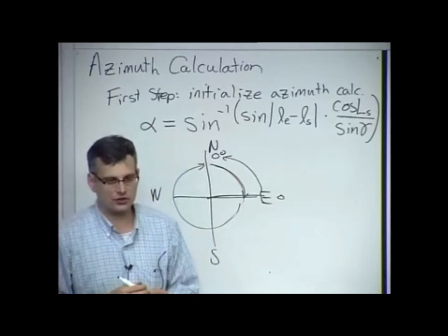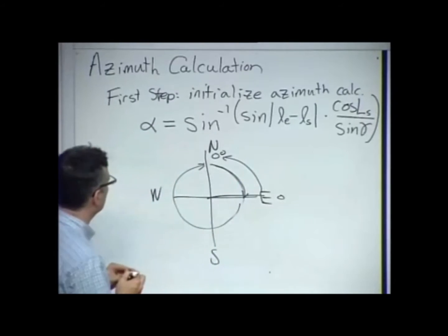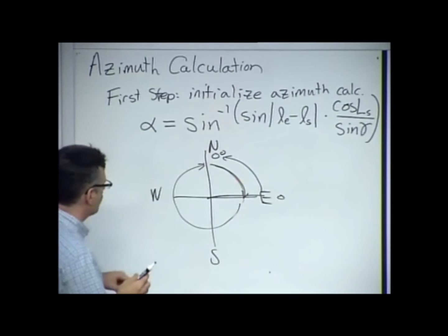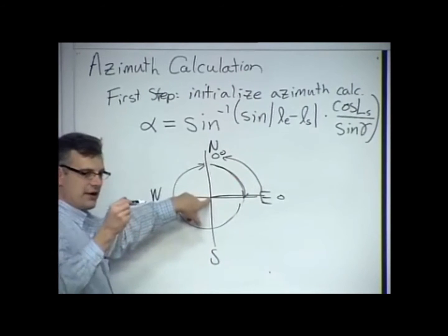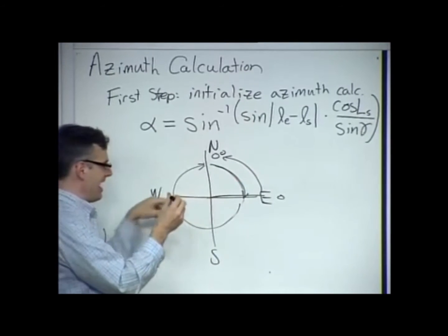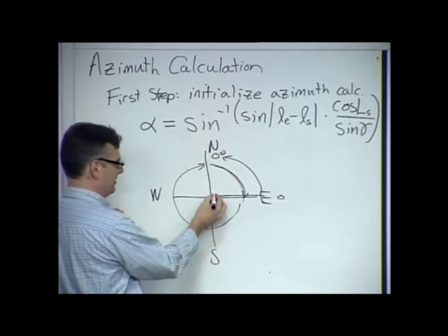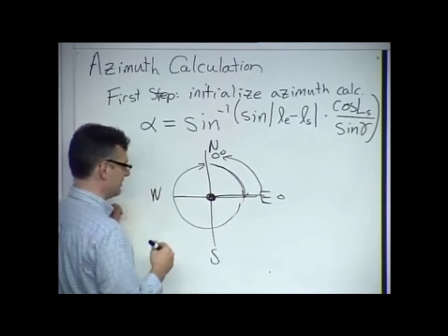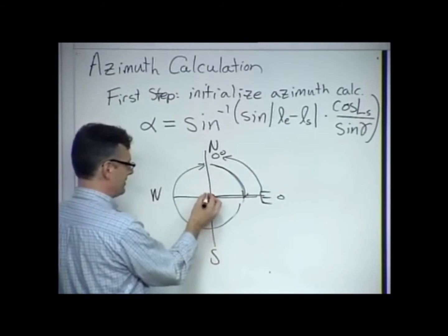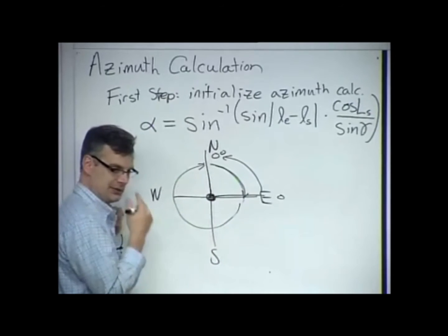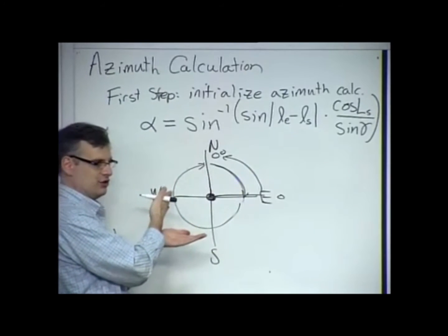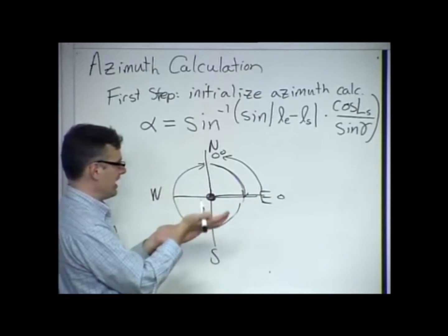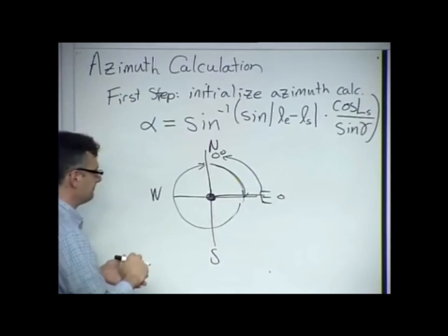Yes? The east-west part, that's at the equator on the field there? Oh, no. So this is actually looking down from above, right? And if you imagine this is what if you had an Earth station here and you looked at a compass, a good clarification of the diagram. If you just looked at a compass, you would have a north, a south, and an east and a west. And so the azimuth tells you where along that compass bearing should I actually point the dish antenna.